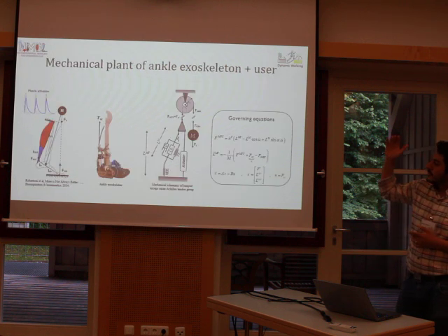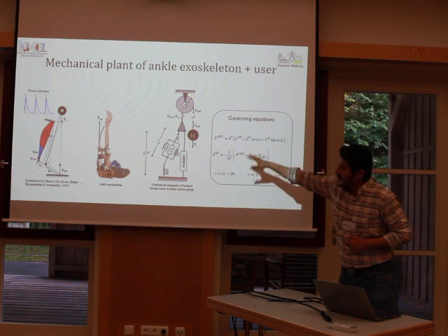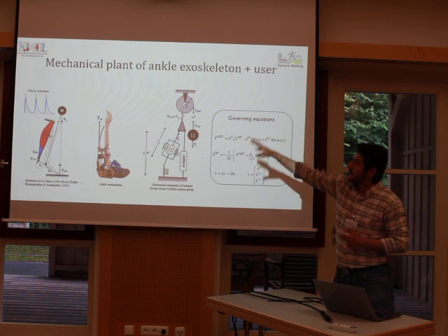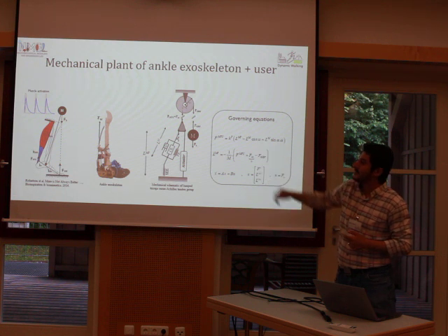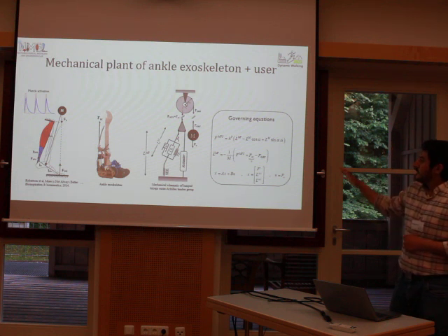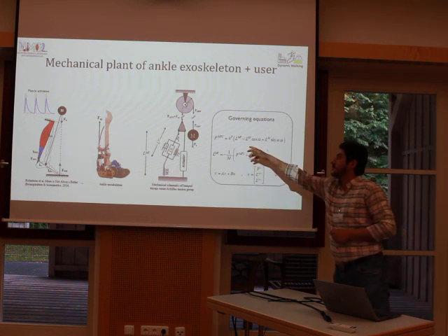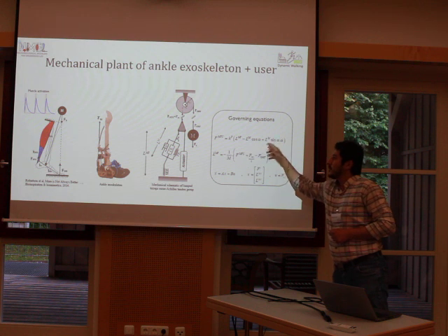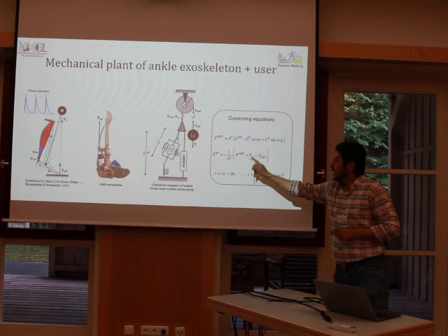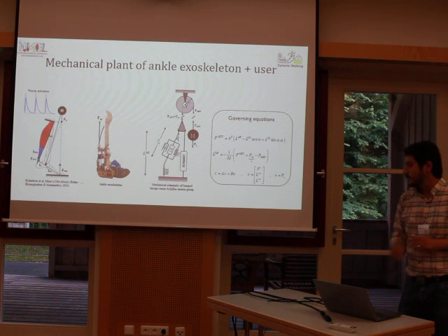So wrapping up, we're going to control the tendon force using JLO. This is the system. For hopping, we can simplify the model with this mass and spring system. I can show it to you after the presentation if you want. And we can obtain the governing equations in state space form. Because we have a closed-form equation for the tendon force, and we can write the equations of motion of that mass, we can have the system's equation in state space form, which is very good for model-based control.